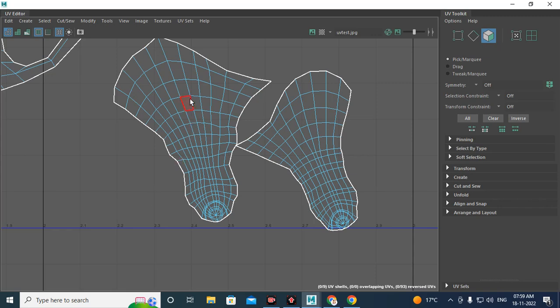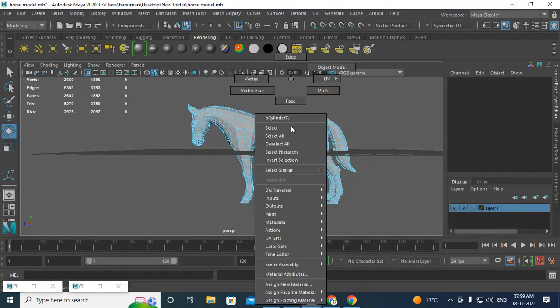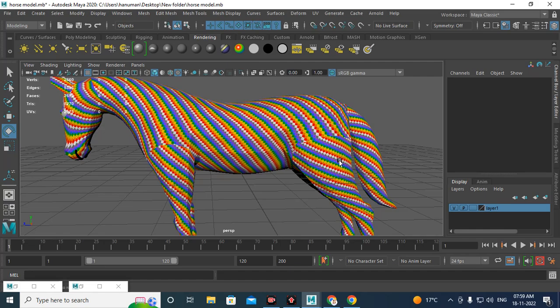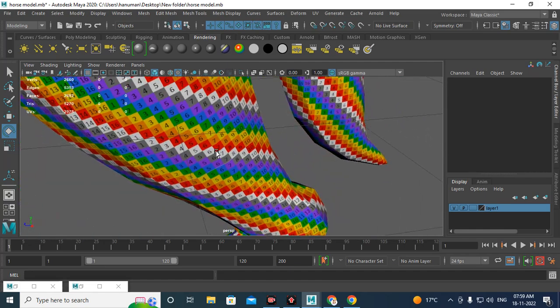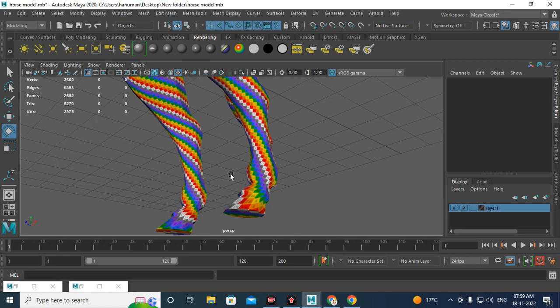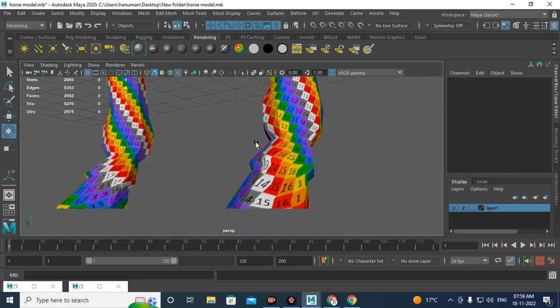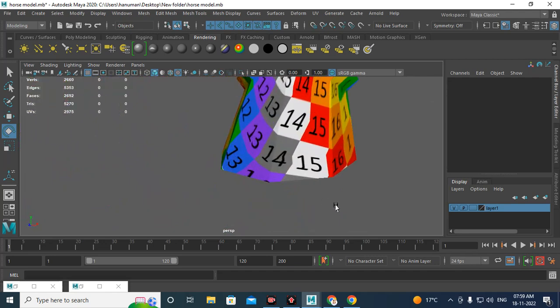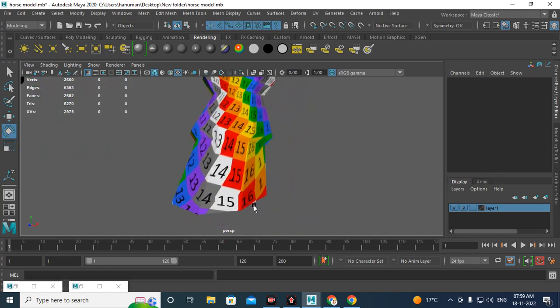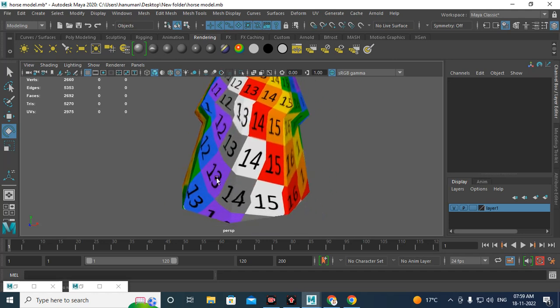Otherwise, at some places the tiles get smaller and at some places bigger. If I use the map, see the map exactly, it is almost the same in all places. The tiles should be equal squares. That is called texel density. Texel density should be equal at all the places. But here it is not matching. See this? They are stretched.